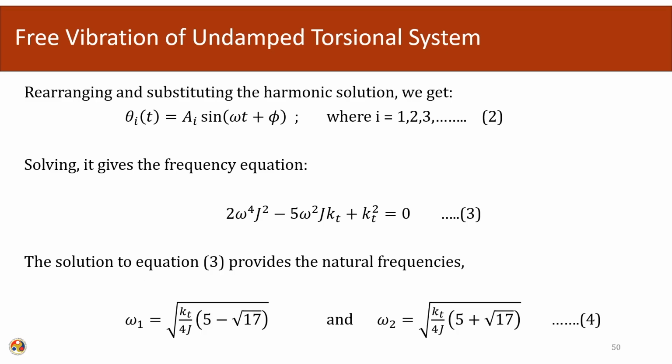Again, remember for x, for each degree of freedom, we said that the motion is a summation of all the individual components multiplied by a time dependent coefficient. Each mode is going to contribute, so the total motion will be the contribution from each mode multiplied by a time dependent component.